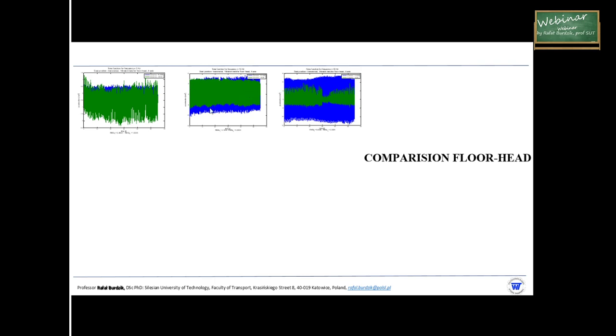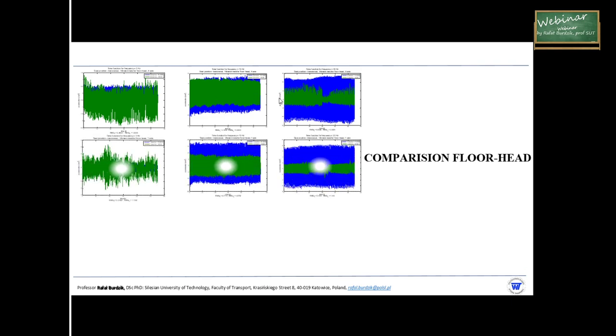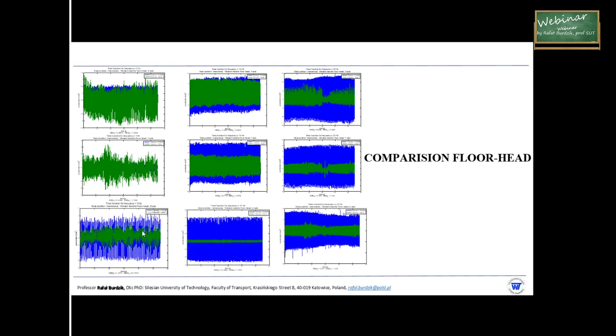Yes, if we consider the 15 Hz, which corresponds to the unsprung mass resonance, which is most important to the comfort, we can assume that it is 0.9, yes, transfer factor. But if we consider the highest frequency, which is 30 Hz, the transfer factor here would probably be about 0.3. So that is how it works. The same situation is when we consider the y direction, and the same if we consider the vertical vibrations, z-axis. We've got the same situation over here. So it is another example of how we can analyze the comfort based on the different location.